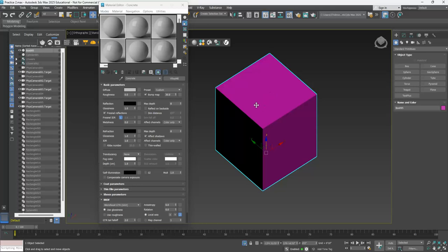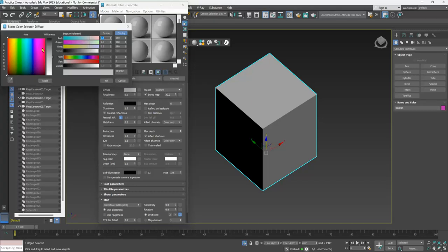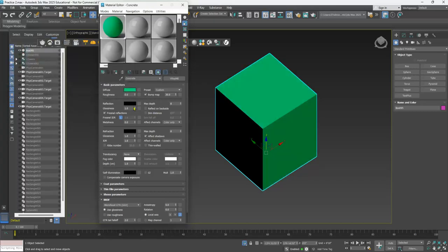So there's two ways to apply it. If the scene is very simple, you can drag it and drop it. If it's very complex, you can select it, and you can go here to this one, which means assign material to selection, and I can assign it. Both have the same option. And you see the material is currently gray, which is controlled by this diffuse color over here. So if I change the diffuse color to pink or anything, that'll be the color of my box.